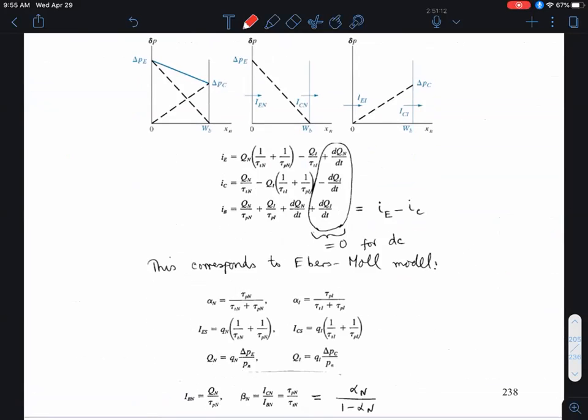So if I was to forward bias both junctions, I get this dotted line, plus I might choose to forward bias this junction, so I get this dotted line. So the overall distribution in the base is shown by this blue line over here. If I forward bias both junctions, the BJT is going to act as a short circuit because the base region is flooded with carriers.